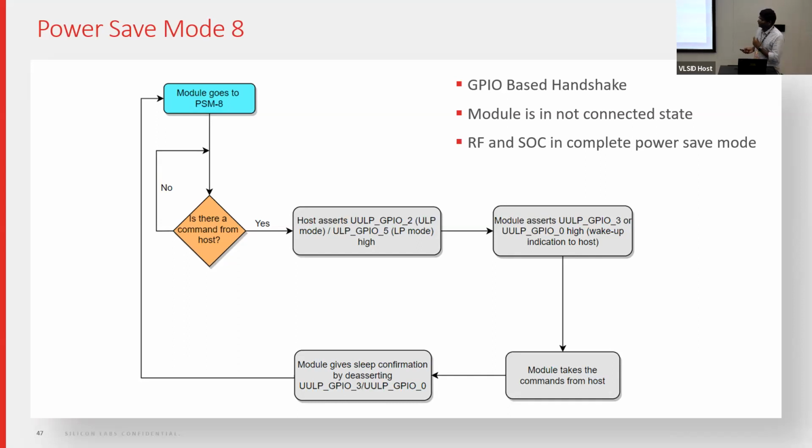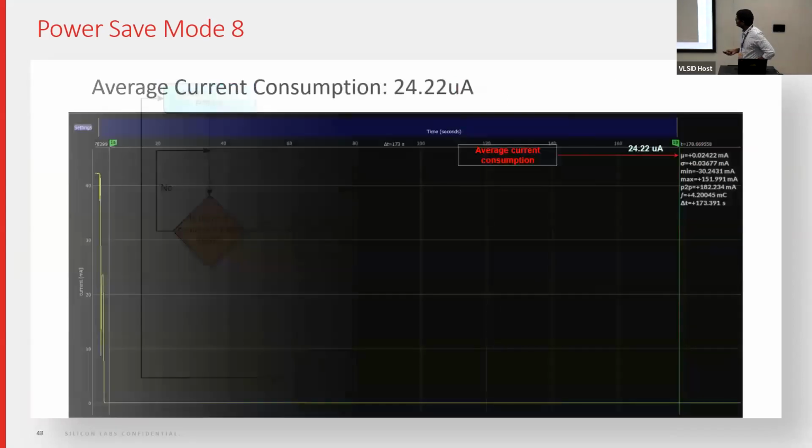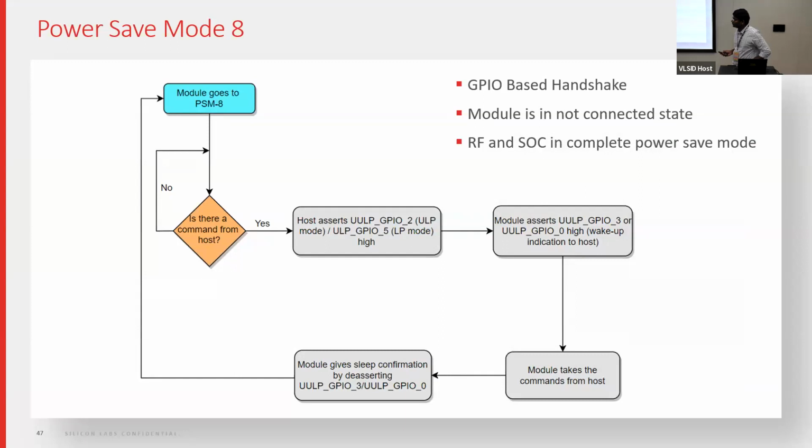When you are saying that the device will sleep, is it disabling the inputs or disconnecting the power? It is only that the connection will be the same. In case of connected mode, the connection will be there, but it is disabling some inputs. Okay, so that means this is only dynamic power saving, not static power saving.